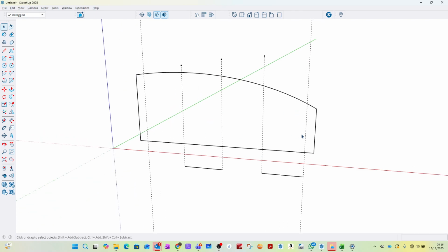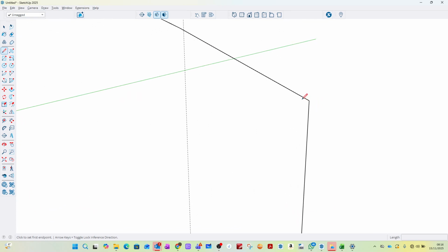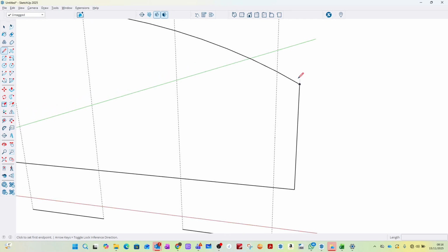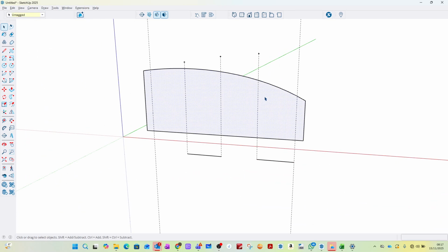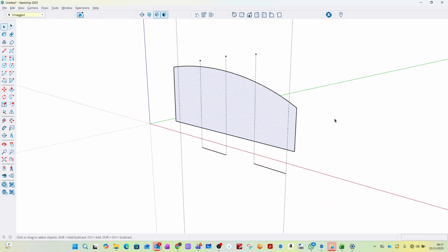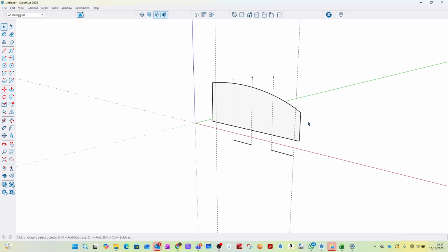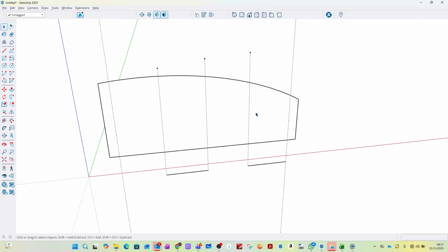We notice these are just a collection of lines, there's no surface created. Now, a quick way to make that into a surface is to grab the pencil tool, assuming that all of your corners are physically connected and touching. This should work. If I draw a line, or make a line anywhere within that shape, just the one line, it will convert that into a surface. At this point here, we can start to move a little bit further forward.